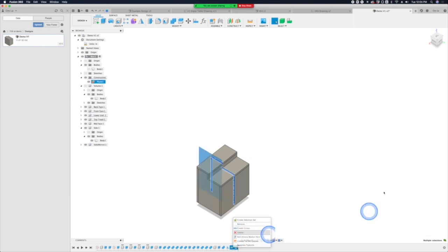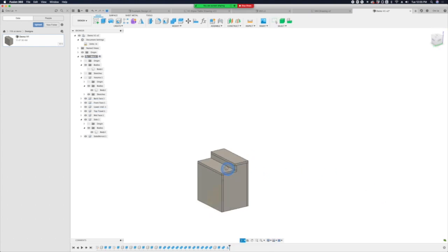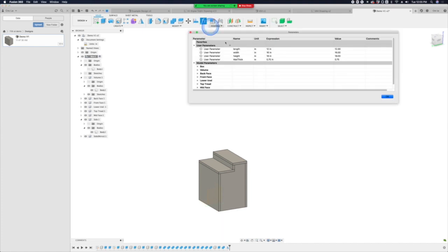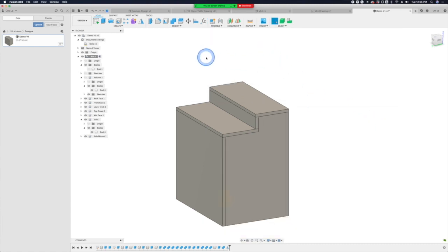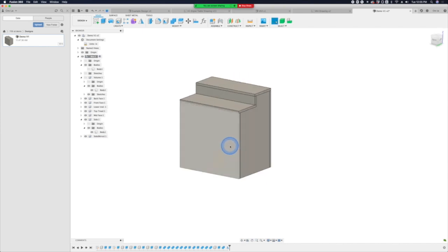Let's say I don't like these, you can delete these features. Done, they're never there. So then, let's see how well this works if I want to change, let's say our material thickness isn't actually 3/4, and we want to do it at a half now. All of these sides now are 1/2 inch. Because of the way I drew it, that's why I like to create a volume and then reduce the shapes, the material thickness from it, because of that feature there.